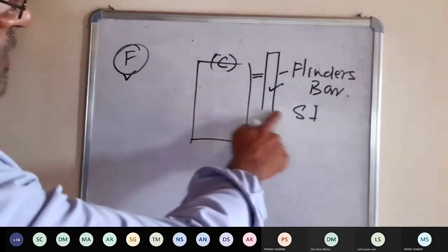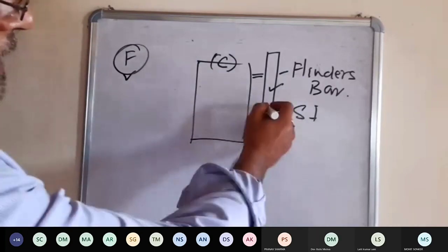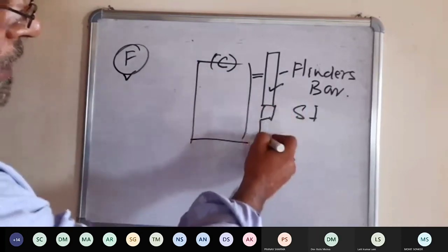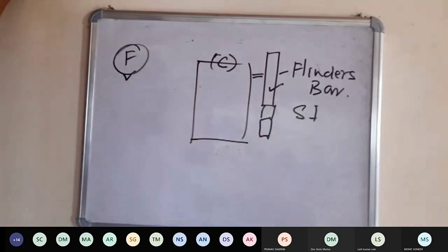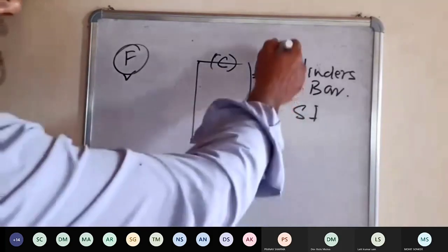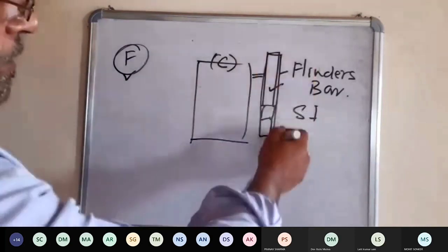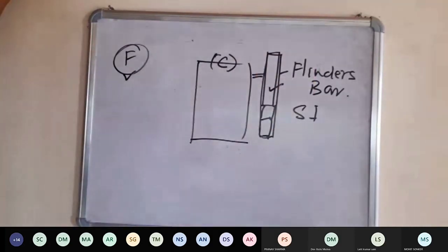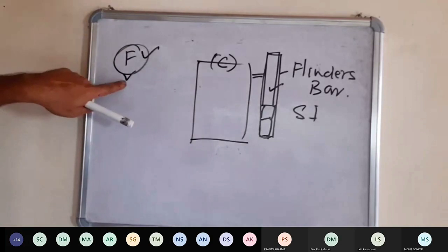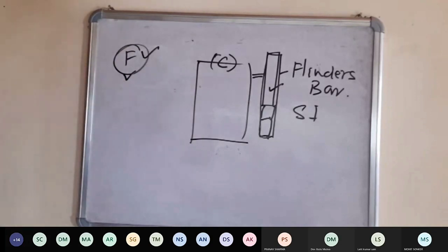So this bar can be smaller or can be made bigger. So this is a cylindrical piece of soft iron, which can be placed forward of the compass for nullifying the effect of the funnel.